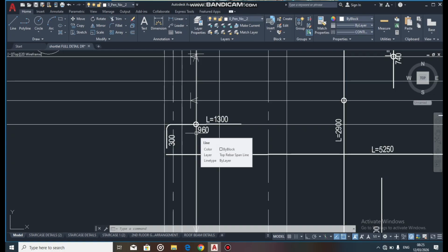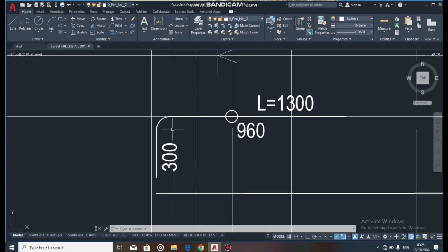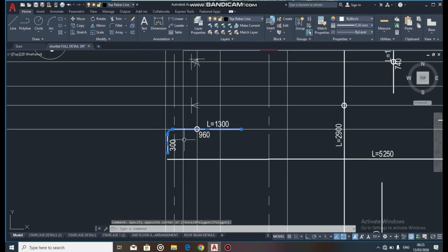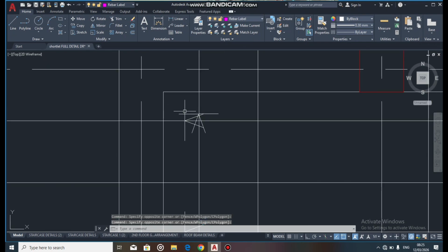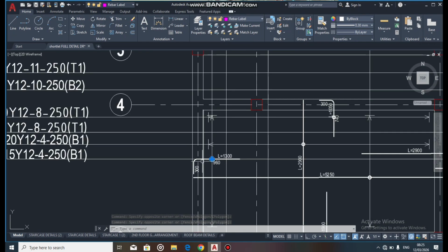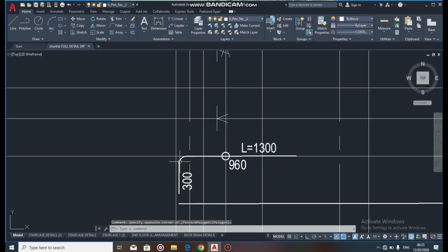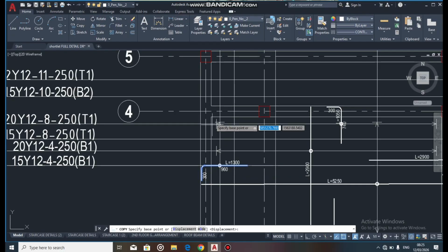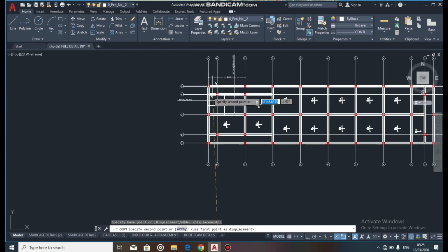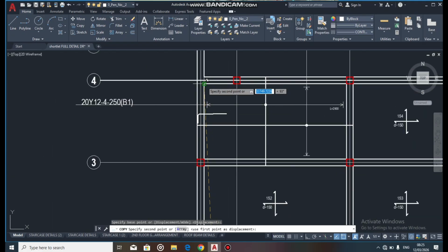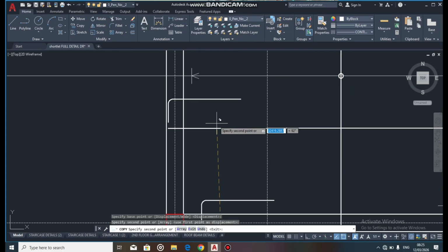If you look at this panel very well, you see that at your left hand side is a discontinuous beam edge. At the top side, you have your discontinuous edge, but at your right and your bottom, you have a continuous edge, meaning that on the continuous sides you have another panel by that side. The sides that are discontinuous, you don't have a panel there.